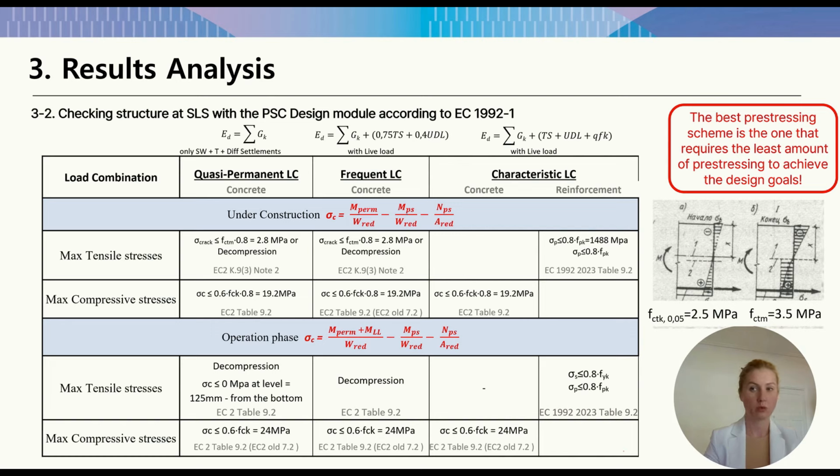Of course, there should be more loads, such as temperature loads, differential settlements, etc. Here it is, main loads. Let's consider the result of stresses at construction stages and at stages when the deck is under live load. I will also show the results at frequent load case and characteristic load case in post-CS.